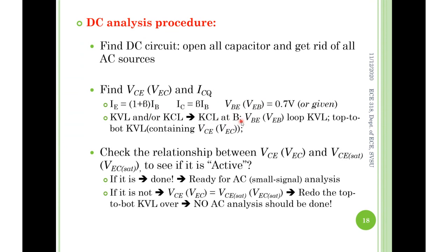You're very likely going to need the voltage at the base, not the gate this time. However, how do you find the voltage at the base? You need to be careful. You are not allowed to use the voltage divider anymore. Instead, you need to use KCL. KCL, of course, works fine for MOSFET too.